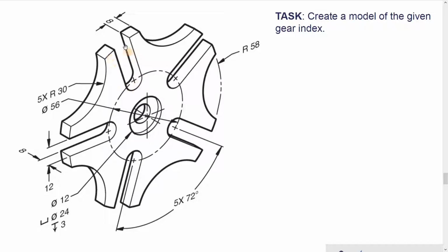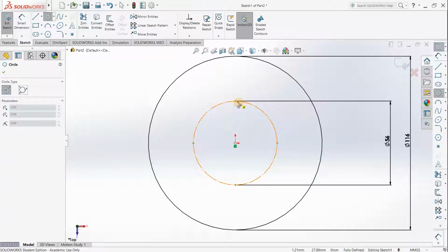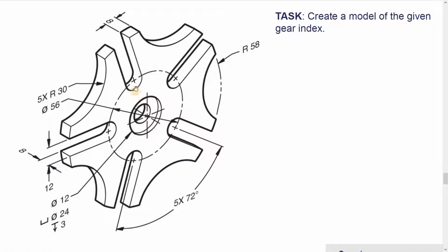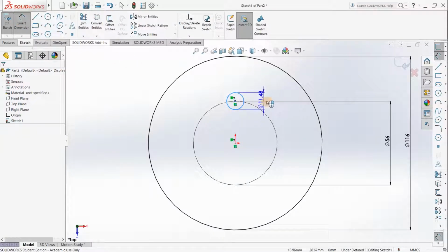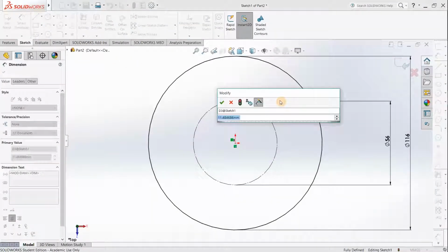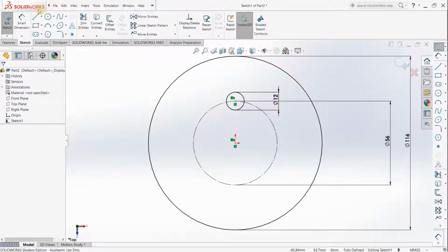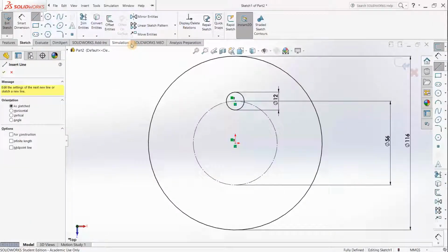Let's create this feature. I'm gonna start from the circle allocated directly on the inner construction circle, like this. To extract this dimension, we go here, you see it's 12, those two parallel lines, which are tangential to the circle, so it's 12 millimeters. And I'm gonna create a line, and those two lines.